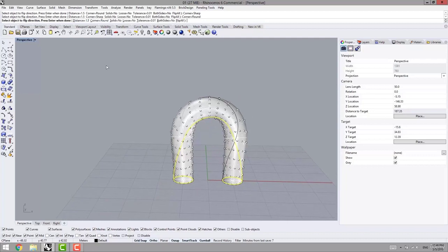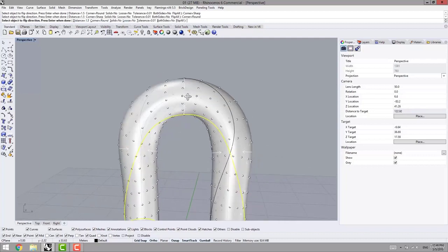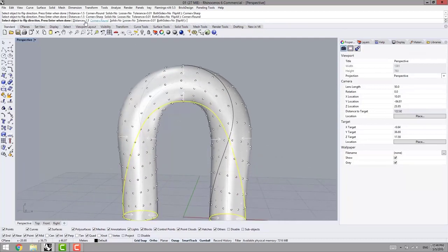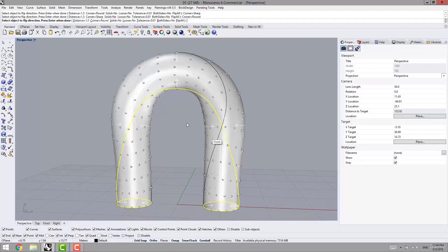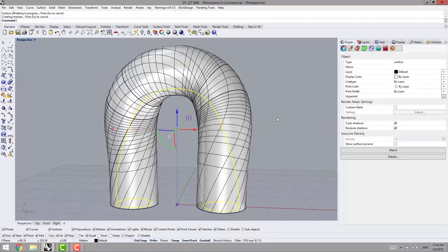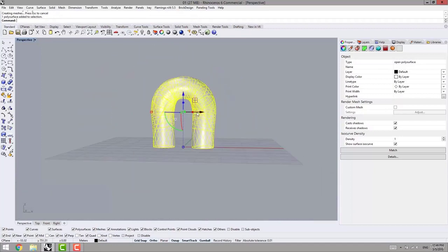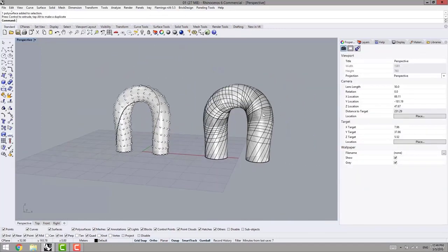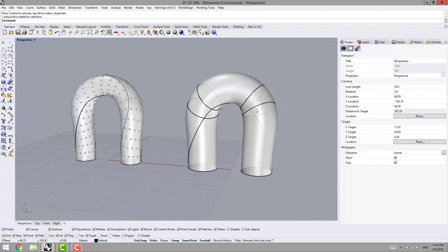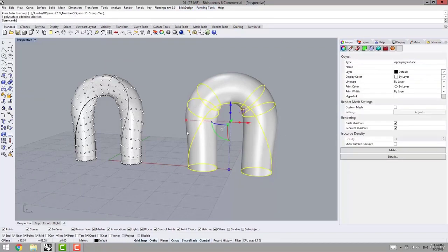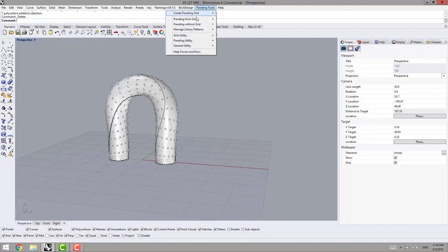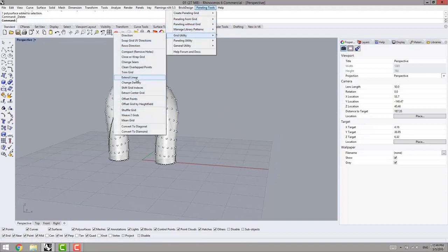on round state. Loose has to be no, and distance 1.5 toward the outside. Now it created a polysurface. When I have a polysurface, I have to make a grid for each of the separated surfaces. So we had better learn the offset point in grid utility.